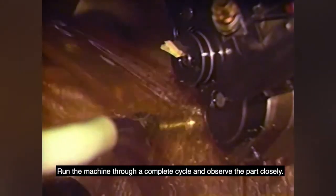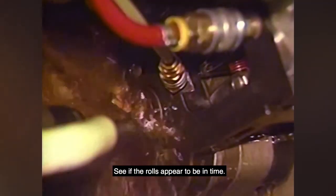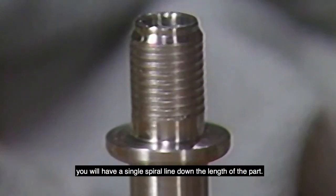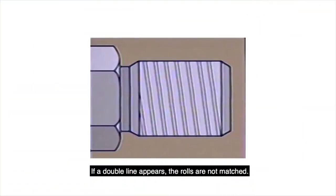Run the machine through a complete cycle and observe the part closely. See if the rolls appear to be in time. When the rolls are correctly matched, you will have a single spiral line down the length of the part. If a double line appears, the rolls are not matched.